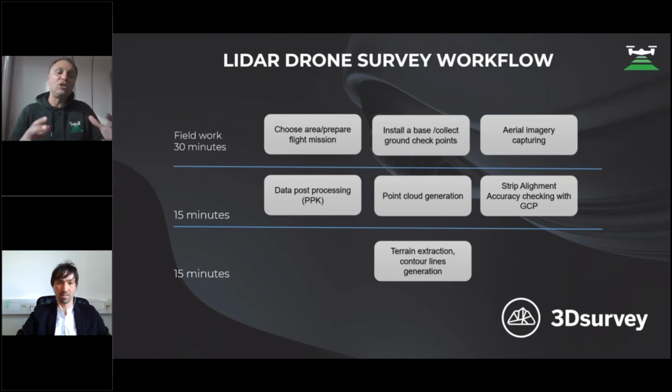You need to get images with high precision coordinates inside, and after that, make aerial triangulation and colorize the point cloud. And if you combine both data sets together, you will get very detailed and amazing results in the future, and you can make maps, very detailed maps and vector layers using both data sets as well.